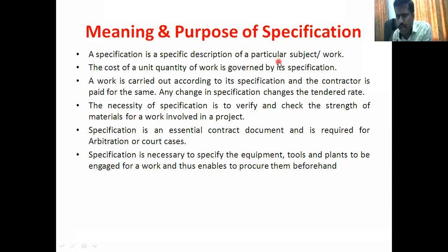And now in the bathroom, we have the fashion of fixing tiles everywhere, covering up to the lintel with tiles. In the case of toilets, we fix the tiles only up to half height, up to the sill level, not up to the lintel. The tiles fixed in the bathrooms like that, we call dados. I'm correct, I think.